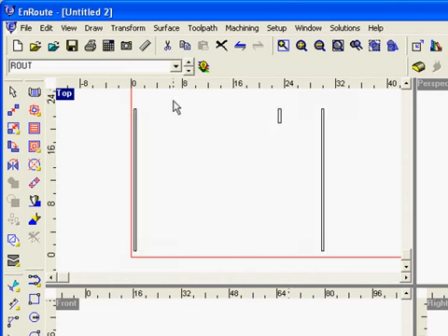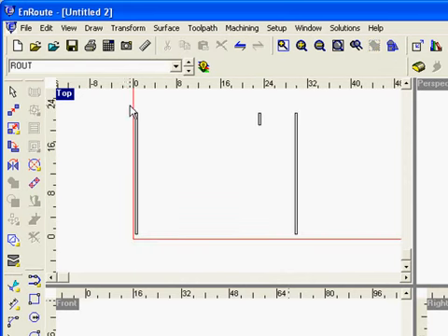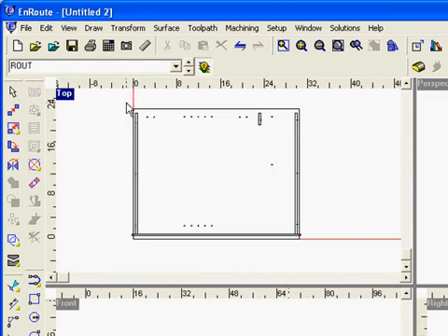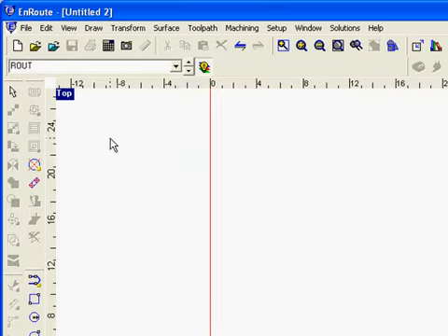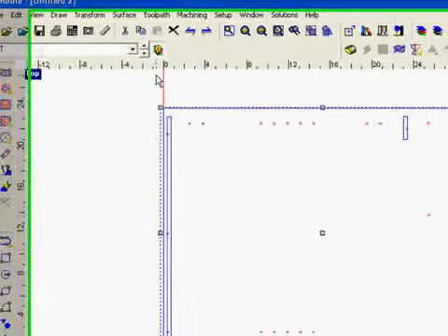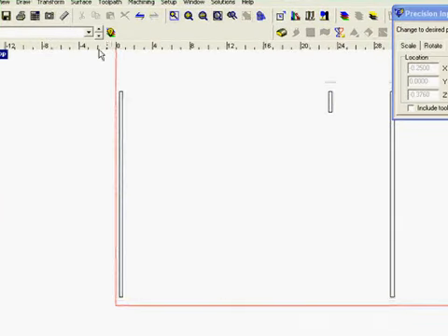And route back and route are both going to use an island fill to cut out the inside of these areas. Some people might use a female offset as well, but an island fill can cover this area no matter how wide it gets, whereas a female offset will only travel around the inside perimeter. So I prefer to use an island fill here. So we need to create 3 strategies. All right, we're going to come here and delete this. All right, and actually we can leave this on screen and just use this to help us here.